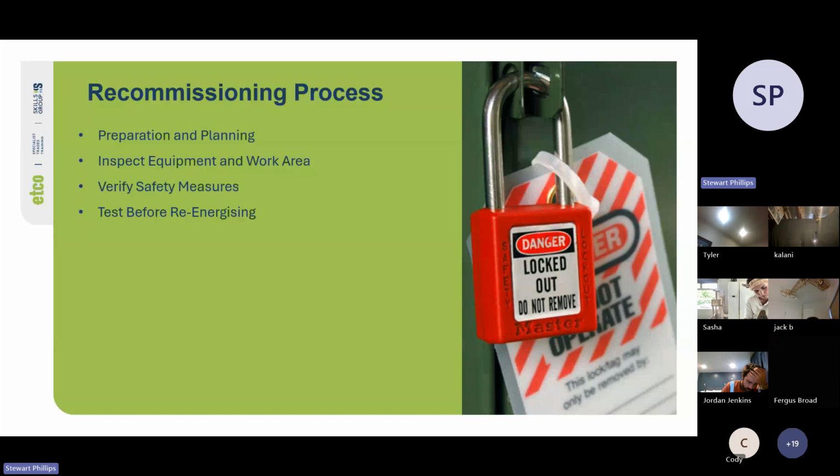Mechanical and functional tests. So operate controls manually, test the control devices, e.g. emergency stop buttons and manual switches to verify functionality. So just a push test, and then test moving parts, test that mechanical components move freely and safely without obstruction or any rubbing or undue friction.